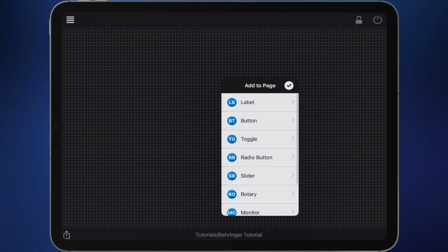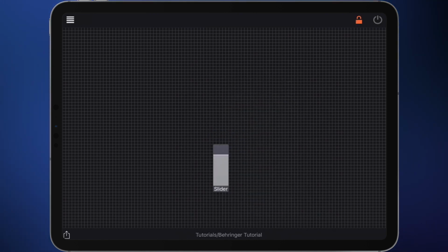Next, you can create a slider on the panel. Make sure the edit mode is turned on. Therefore, check if the lock sign in the upper right corner is turned red. Then you can add the slider on the panel and edit it. To do so, click on the panel and after that on New and Slider. A new slider will appear on the panel.